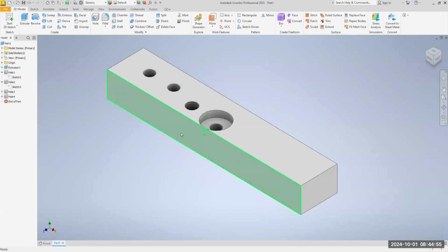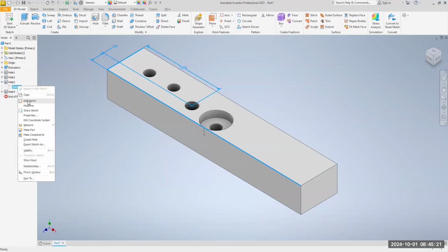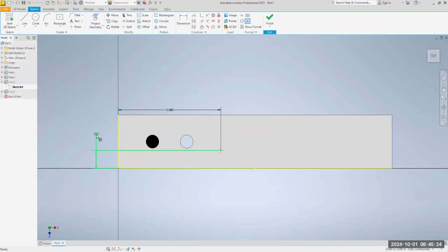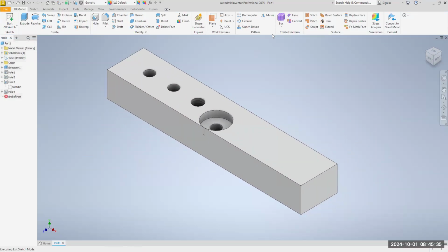See how it's beautiful, how it's easy to make changes to it. And I didn't realize that until I put this hole in and realized I was cutting into the edges here, and that's not what I want. All right, you can collapse these as you're done. We need to now do hole 3, expand it, right click on the sketch, edit the sketch, change it, click on the dimension, change it to 0.75, click on the green check mark, finish. It moved it over. Okay.